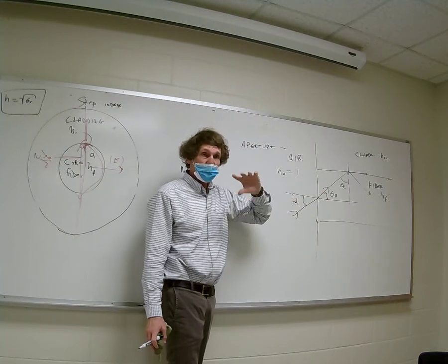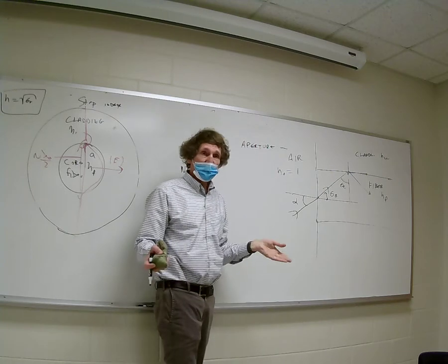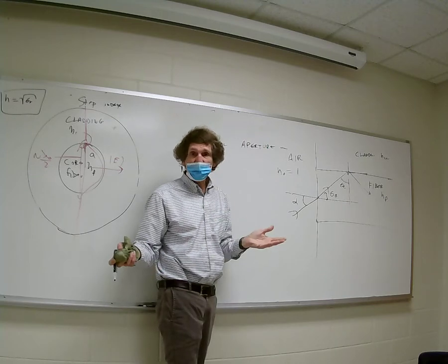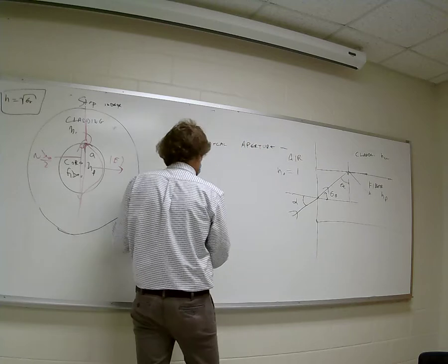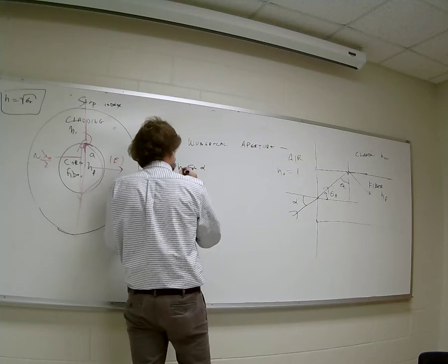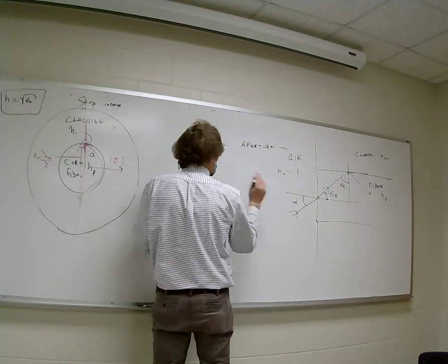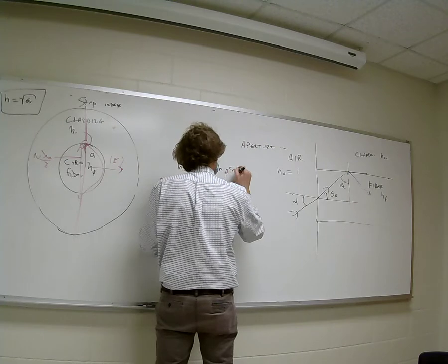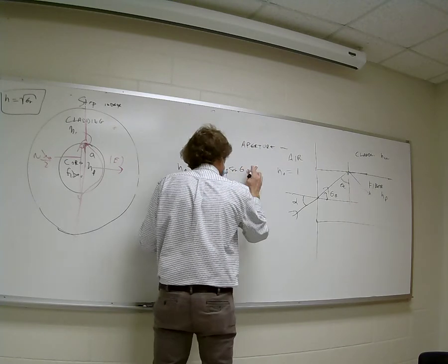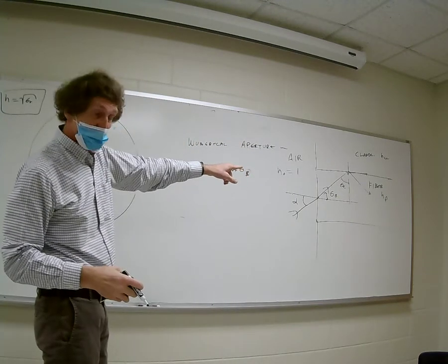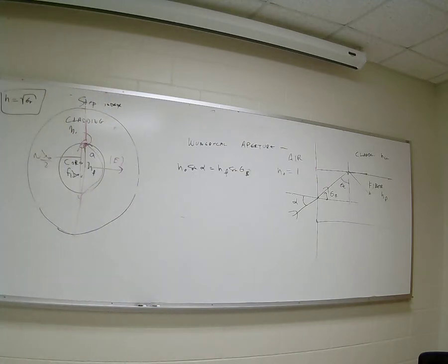Now I could put down beta, but beta is omega times square root of mu epsilon. Ultimately the omegas cancel, the epsilons cancel, and you're left with just the square root of epsilon relative 1 and 2, which is the index of refraction. So here what we actually get would be sine of alpha times eta 0, which is usually 1, equal to eta fiber, or n fiber, pardon me, times sine of theta b, right? You can see what I'm going to go for. That sine of theta b is the square root of this, isn't it? Y'all follow me? Can you see it okay? Yeah.